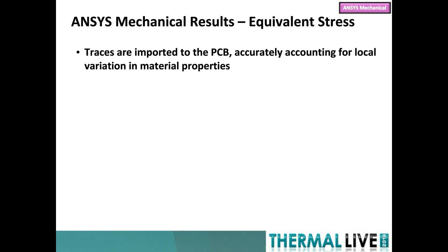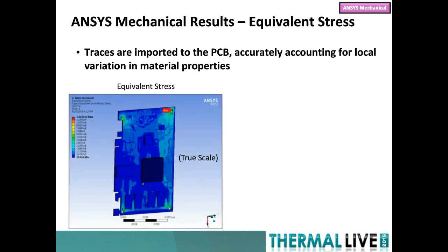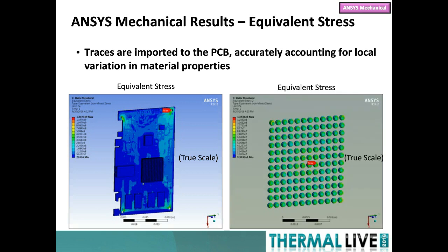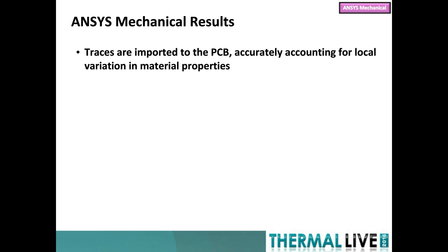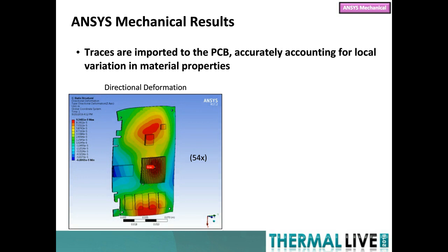The equivalent stress in this board is shown, and the equivalent stress on the package under the cold plate is shown. And finally, some pictures of the directional deformation, true scale and magnified scale, along with the equivalent elastic strain in the package.